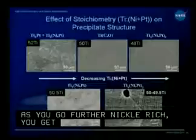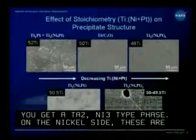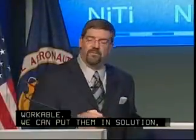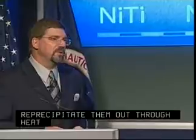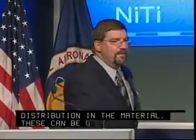Now the difference is that on the nickel rich side, these precipitates are workable. We can put them in solution, we can reprecipitate them out through heat treatment, we can control their size, their volume fraction, and their distribution in the material. So these can be good actors for us. So if we go to the next slide.